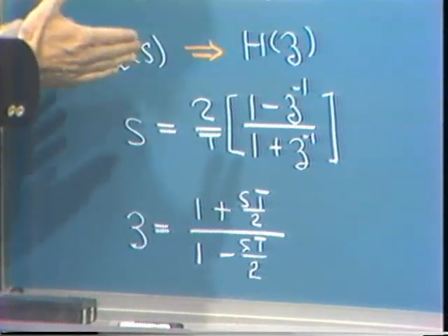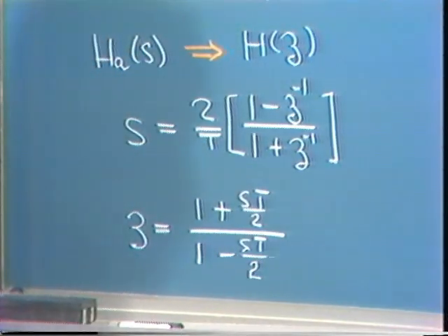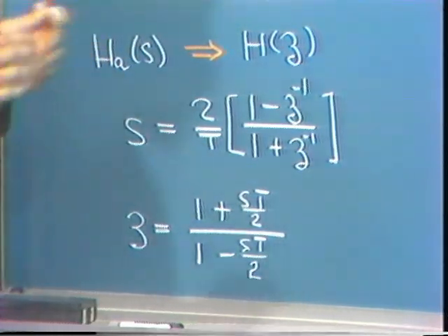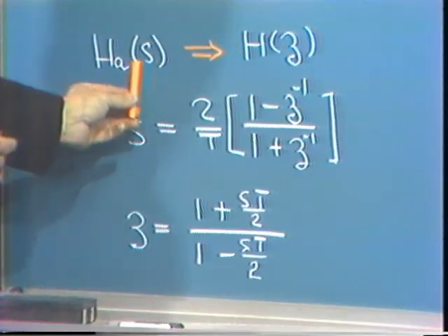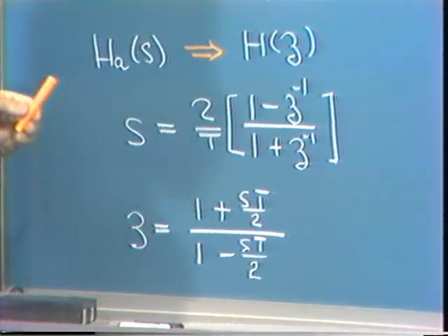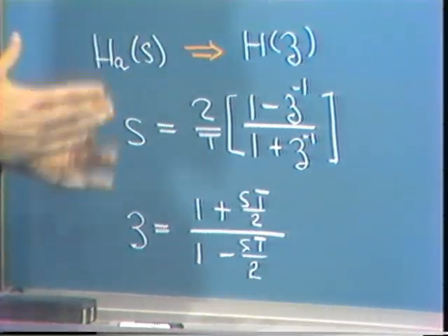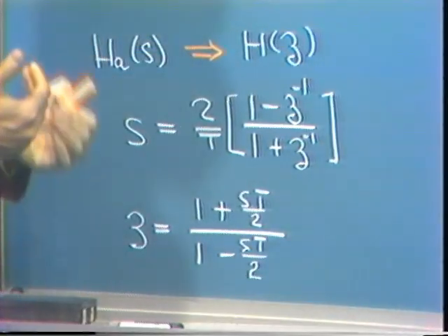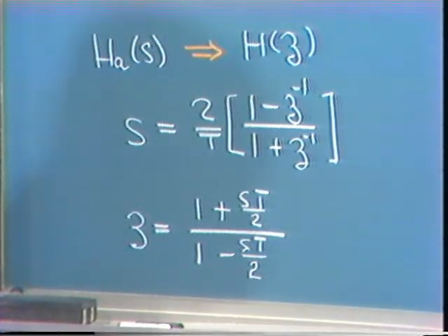So one important aspect of this then, which in fact is different than the impulse invariant procedure, is that it in fact does correspond to a mapping from S to Z. It's a mapping of the S-plane to the Z-plane, which is not quite what the impulse invariant method is.